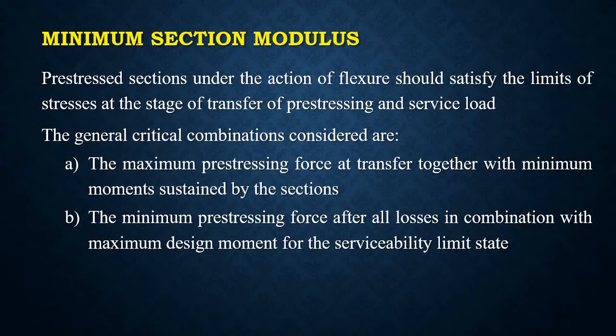Under that, the first one is minimum section modulus. Prestressed section under the action of flexure should satisfy the limits of stresses at the stage of transfer of prestressing and service load.